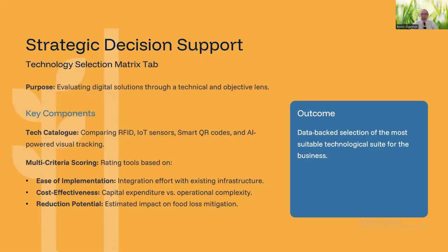In this stage, the prepared materials and selected technologies are physically implemented in the field. The application is carried out in three main phases with predefined standard operating procedures. In the first phase, the synchronization of existing physical stocks with the digital inventory is ensured. The first digital count is performed using the SKU codes defined for each product group. In the second phase, the IoT sensors are mounted at the designed critical control points. Technical precision is at its highest at this point. Sensors are placed at mid-shelf levels representing the actual temperature of the product, rather than at points receiving direct airflow.